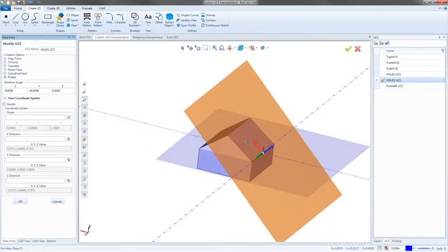But really what you're going to be using these for is pretty much just whenever you need to work on a different side. This is also a good way to set up index systems. If you're ever doing any fourth axis and you got some indexing to do, you can set up a custom plane and then index. You can actually select the index off that plane. So UCSs are a big function. I would say more so when you get later into the software, when you're learning about more and more. But it is a very cool feature. And the rotation is just going to let you rotate an existing one.